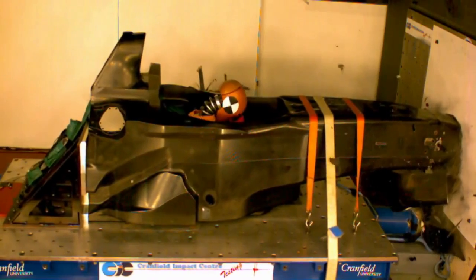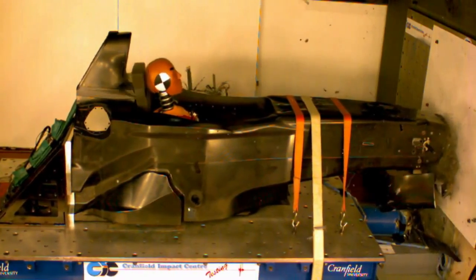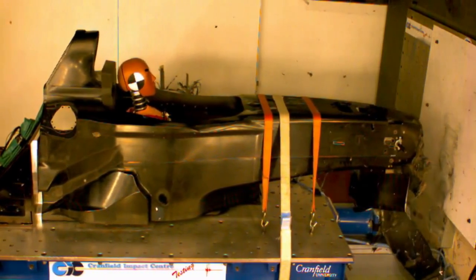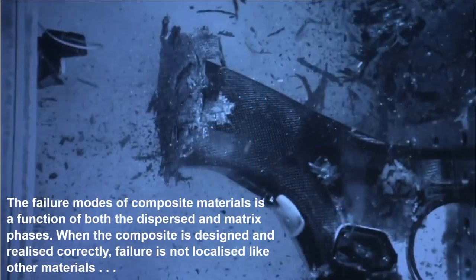Here's another one. A different layup, different components, but the failure mode appears roughly the same. It fails everywhere at once. As we've just seen, the failure mode for composites is both the combination and culmination afforded by the matrix, the dispersed or reinforcing phase, and the interaction between the two. If one gets things just right, then the entire composite will fail in a brittle manner, as opposed to one select region as we've seen with other classes of materials.